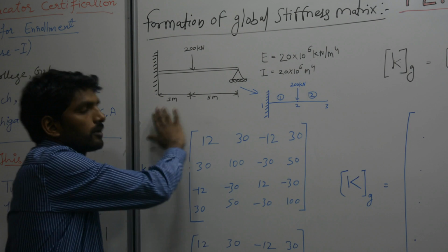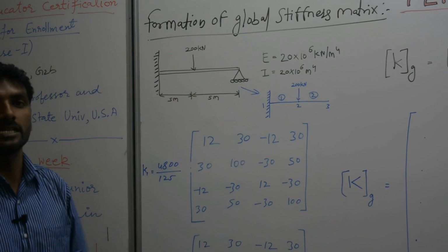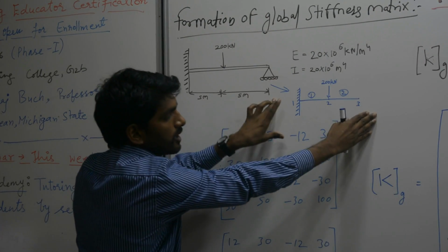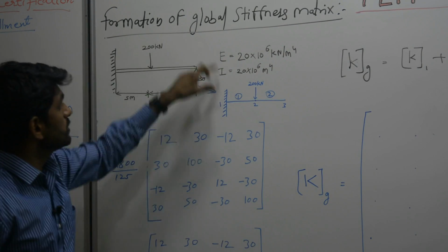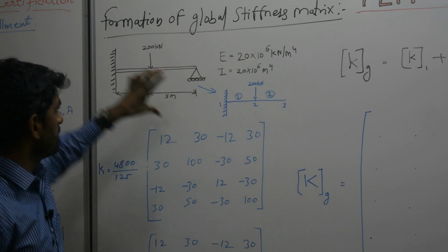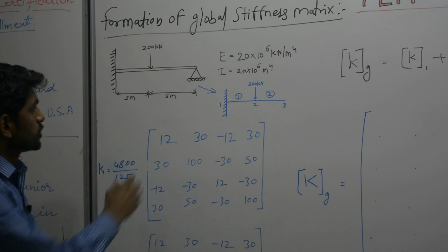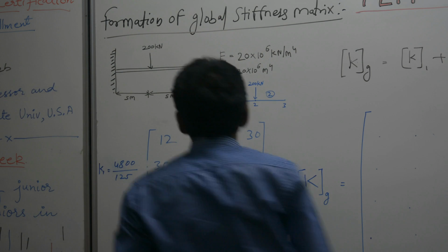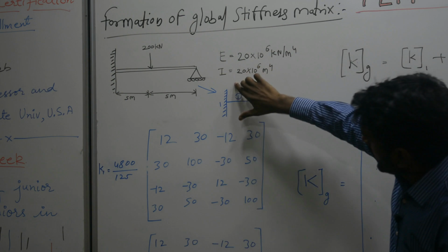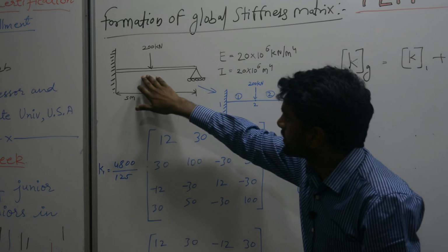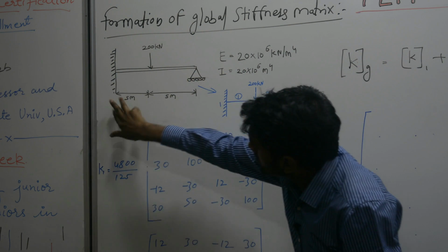Now to solve this problem, firstly I need to follow step number 1. In the last lecture we have already covered step number 1, called discretization of your whole problem into small elements and configuration of that. Because we are using a one dimensional problem for solving the beam problem, I have modeled this beam using a simple one dimensional bar. So this is our simple bar. We have firstly noted the numbering of the elements because there is a point load, and we also see that there is a discretization between the elemental length.